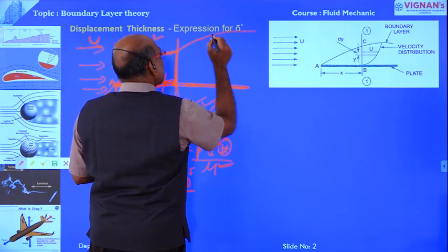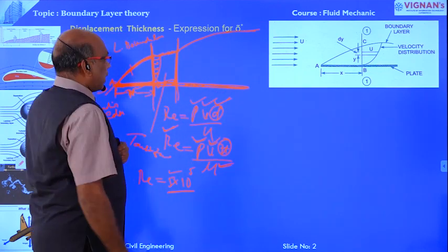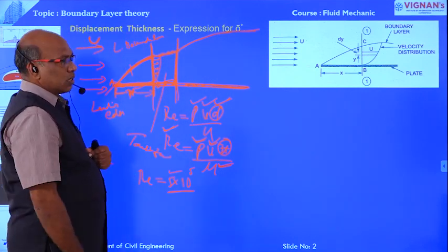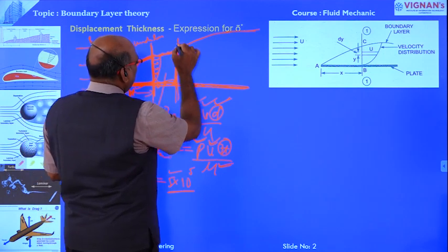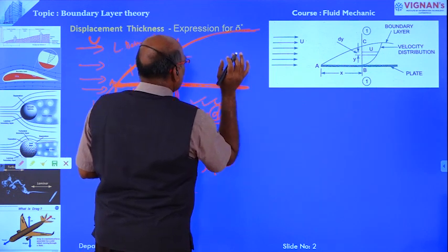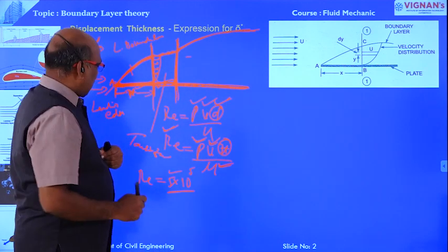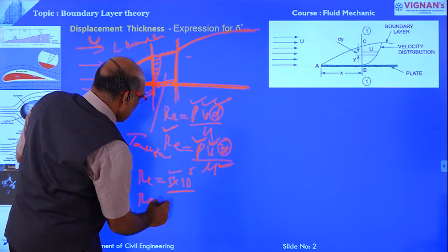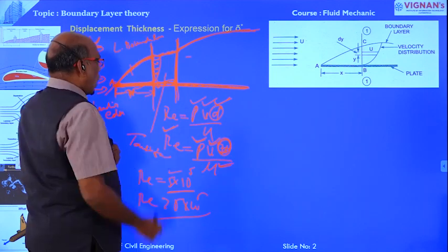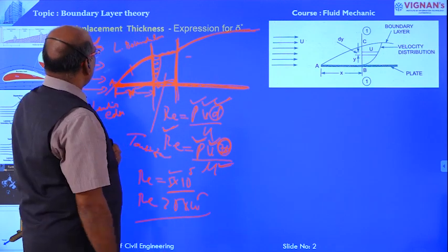Now beyond the transition zone, the boundary layer thickness continuously increases, and the flow in this zone is disturbed, very random and turbulent. Therefore, this zone is known as the turbulent zone. That means when the Reynolds number is more than 5 into 10 power 5, beyond the calculated distance x is nothing but the turbulent zone. One more zone is here.